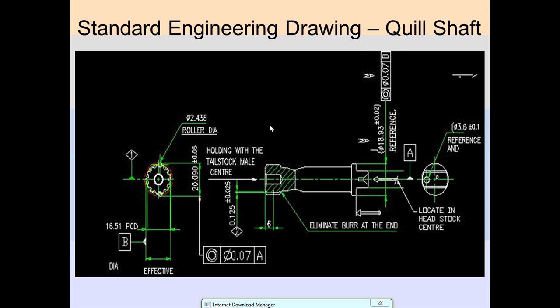This is the diagram which we have made from the CATIA software. In the quill shaft, we can see how much axial play and how much radial play. Axial play maximum allowance should not be more than 0.70. In the quill shaft, the dimensions occur in 0.7 to 1.40 mm. This is the separate part of the whole matching process. You can see quill shaft separate, bearing support shaft separate, and the driven shaft separately.